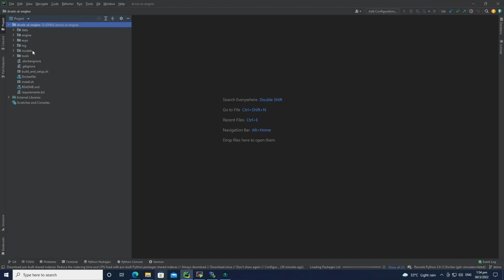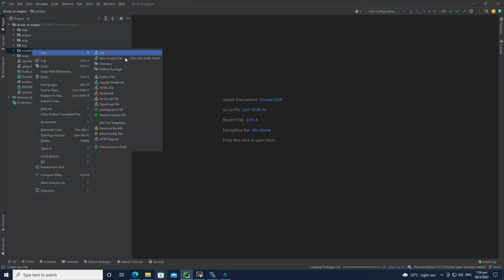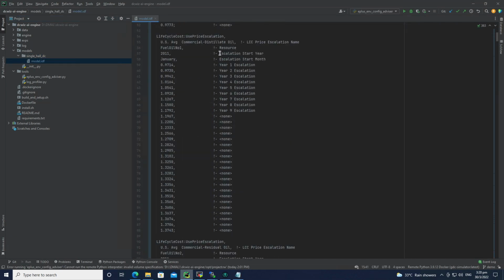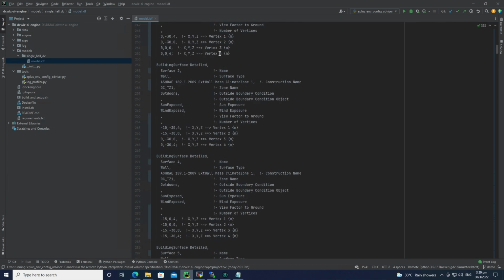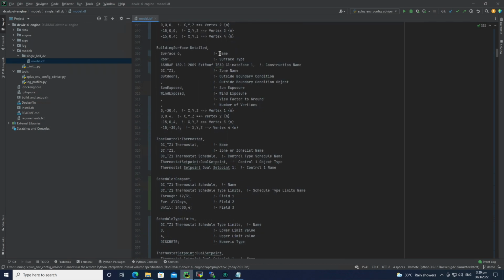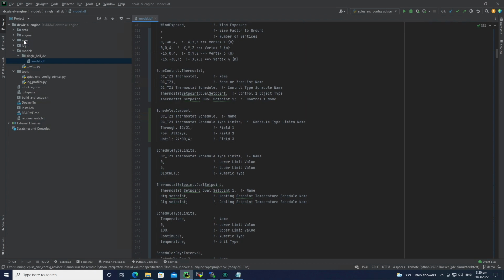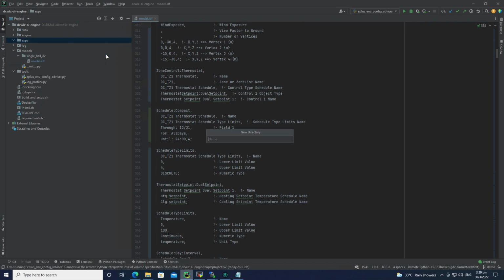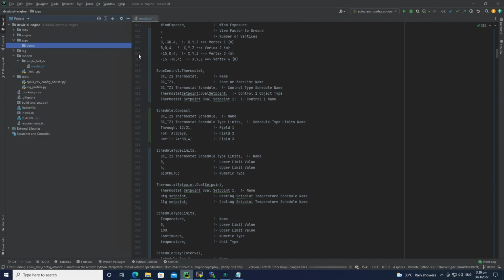You can also pull our public image so that you don't have to build locally. After setting up, we can create a folder under Models, which represents our data center. In this folder, we put the DC modeling file obtained from building professionals. It is a standard modeling file that does not contain any ML-specific information. After that, we create a folder under experiments to store the configuration and our experiment scripts.